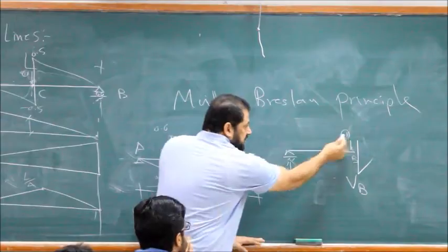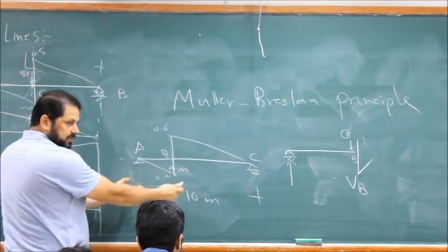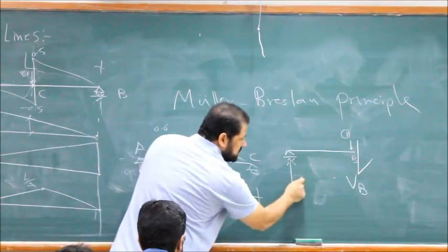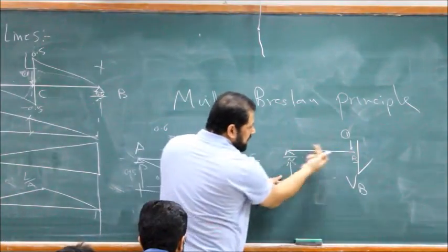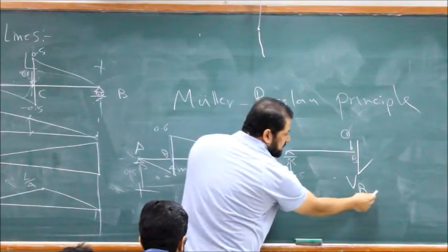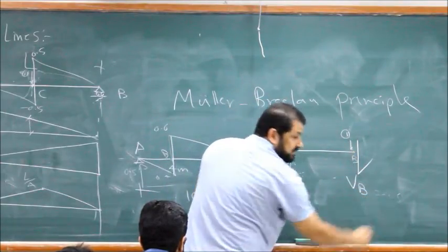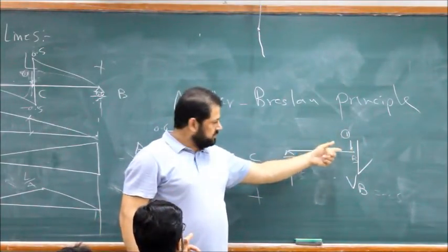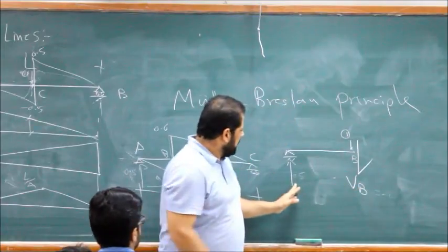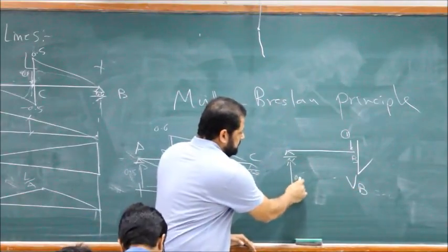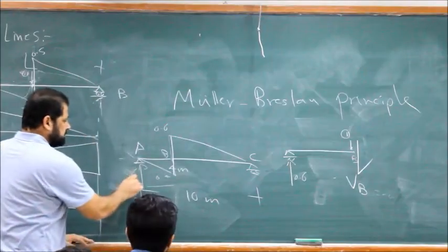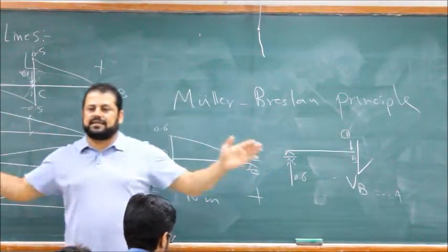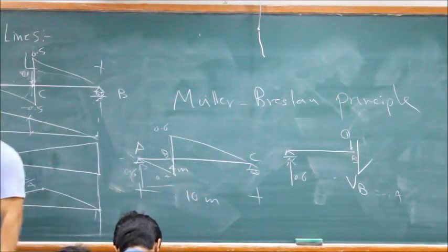If the unit load is here, from the equilibrium you go back to your beam. This is 0.5 in this case, for this location. If this is 0.5 and this is 1 down, then this one is minus 0.5. Should be the other way. 0.4, sorry, and this is not 0.5, this is 1.6. This is 0.4. The sum of the reactions at any point for any influence is 1.